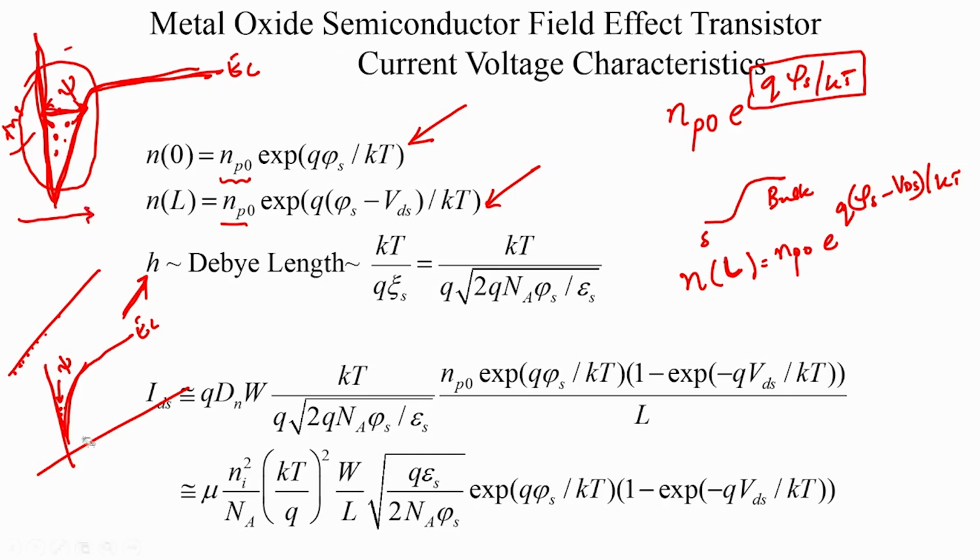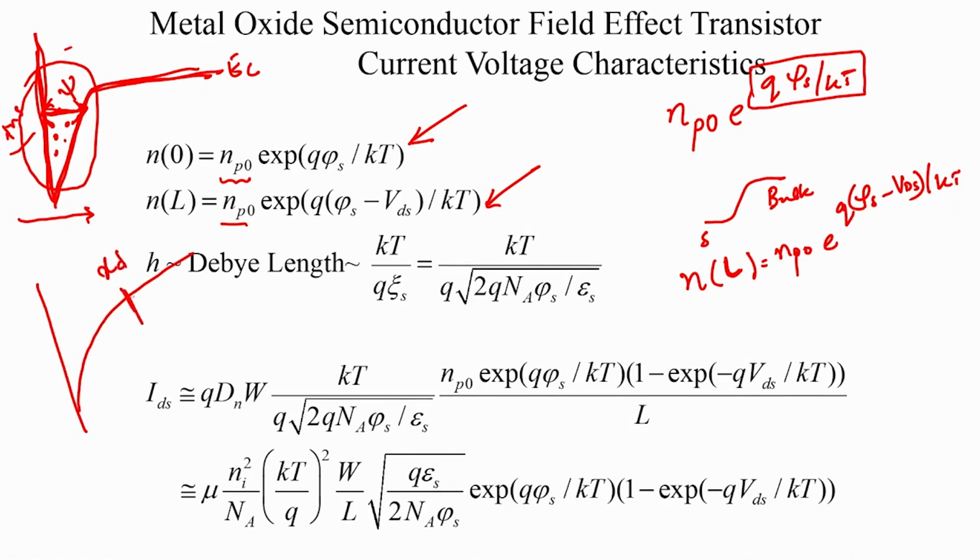So, you have your band bending in the semiconductor because of the applied gate. You have the insulator there, and due to the applied gate voltage, you have band bending in the semiconductor, and beyond a certain point xd our bands become flat. But once the electrons appear at the interface, what is Poisson's equation?